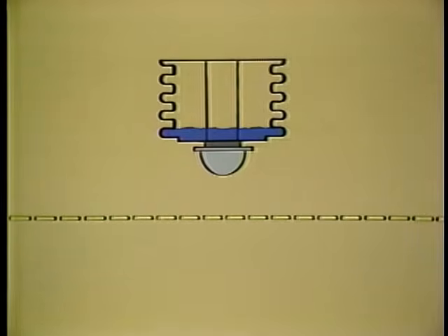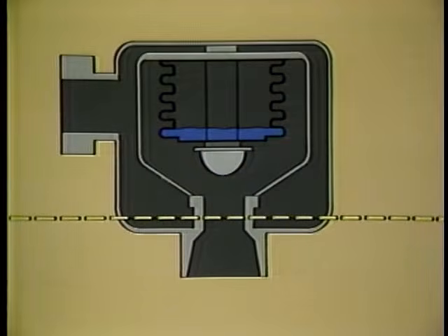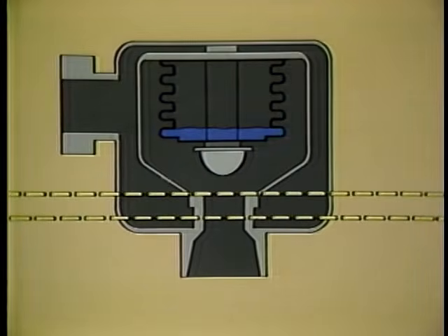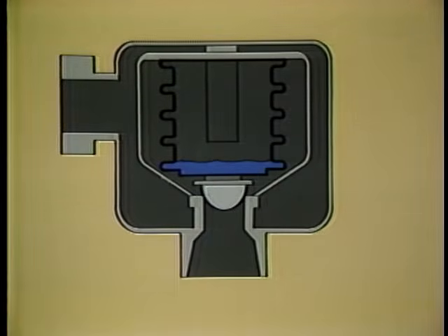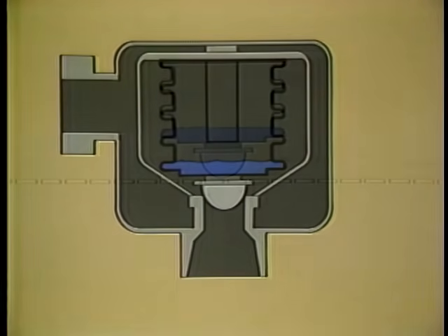Only water is used as the bellows charge of the trap which will fail closed, and the valve is positioned to seat just short of the bellows free length. If the bellows ruptures, it returns toward its free length and the trap is closed.